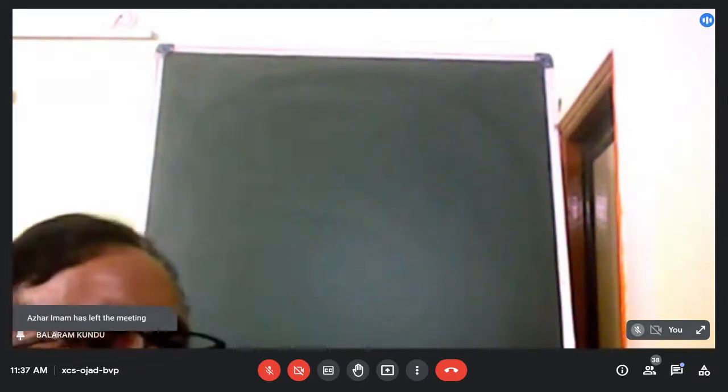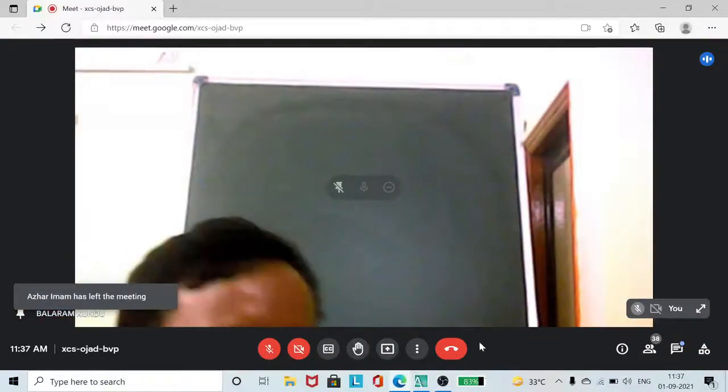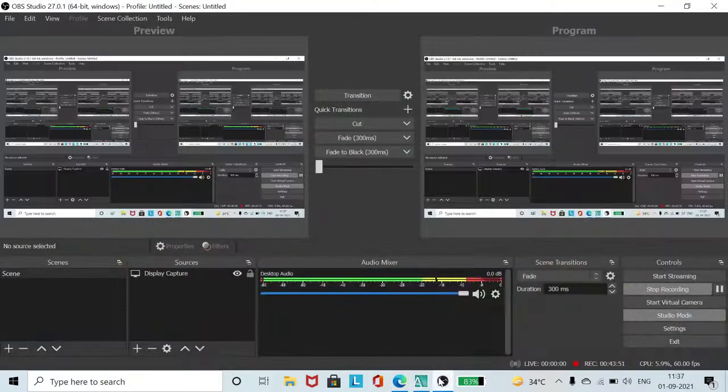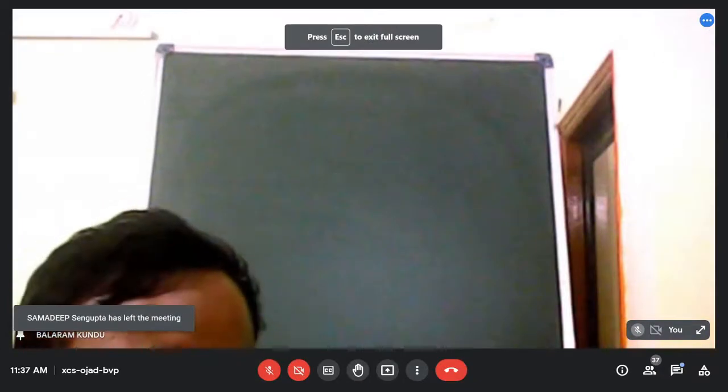Temperature gradient exists, only then will heat transfer happen. Temperature variation is there, so the diffusion part should be there. In convection, the diffusion part should be there if advection is present. So convection has two components, diffusion and advection, and these two parts should be there. Understand? What am I trying to say? Hello?